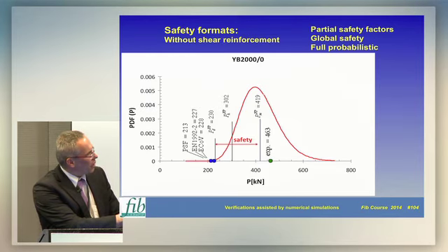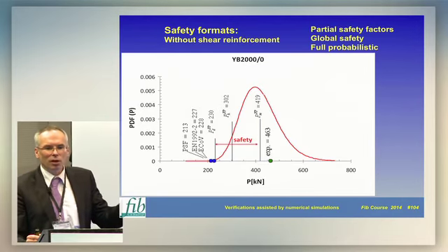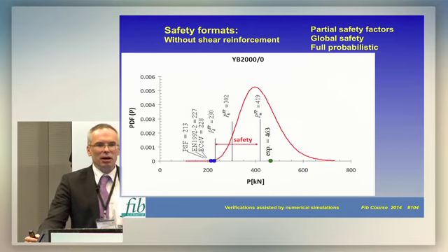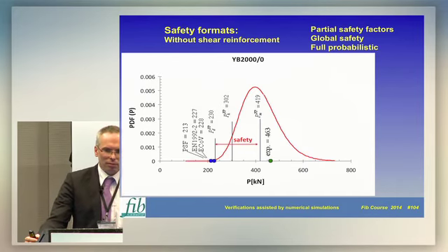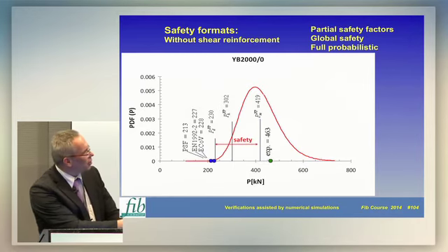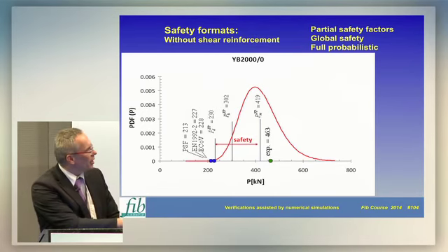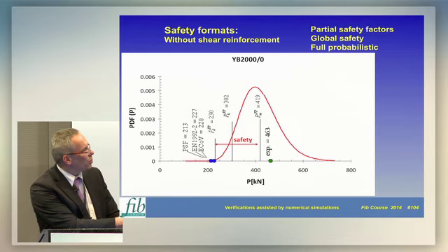So that method where we use the partial PSF means the partial safety method. That is the method when we use material design parameters with the safety factors in the nonlinear analysis. So this gives this 213 design resistance using the Eurocode, this value, using this coefficient of variation approach where we have two analyses. We are somewhere here. Then the probabilistic approach was somewhere here. This was the characteristic value from the probabilistic approach. Here was the mean value from the probabilistic approach.